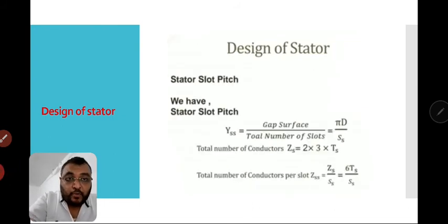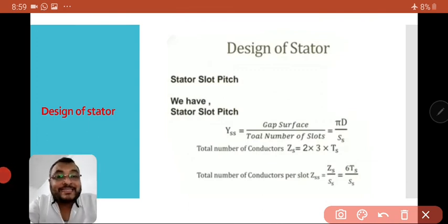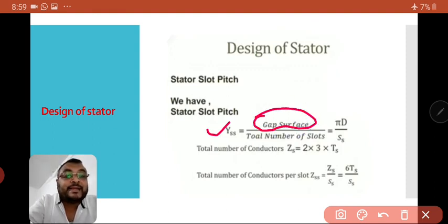To consider the stator slot pitch, we have considered the equation Yss is equal to gap surface divided by total number of slots, which is equal to pi d by Ss. Yss stands for the stator slot pitch. For considering the stator slot pitch, we consider the gap surface, which is equal to pi d, divided by the total number of slots, that is Ss.